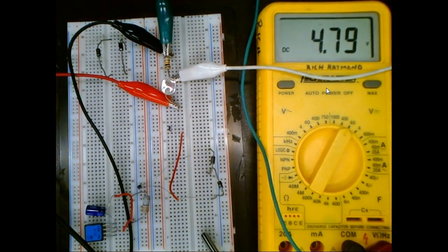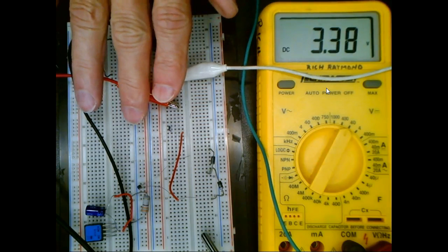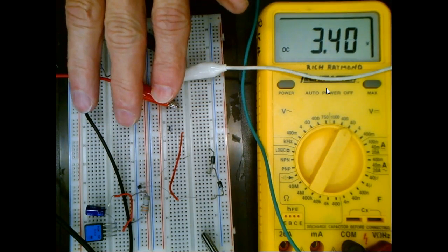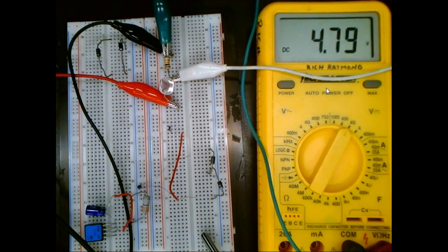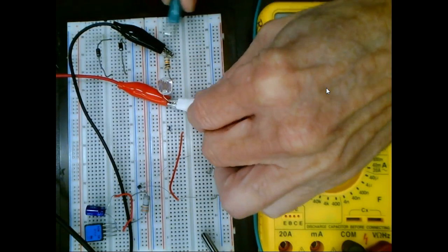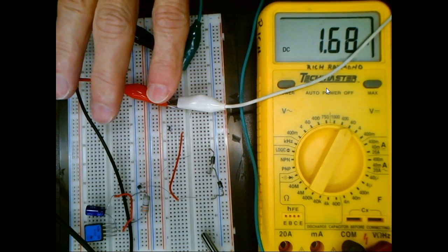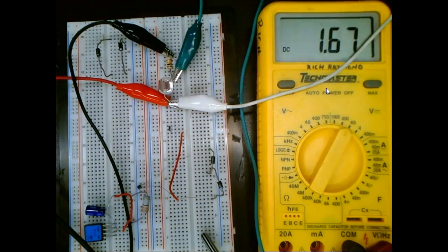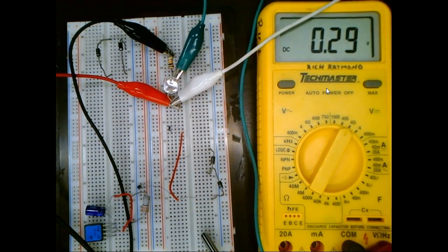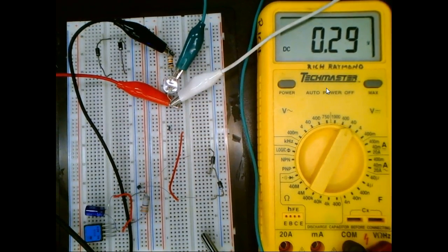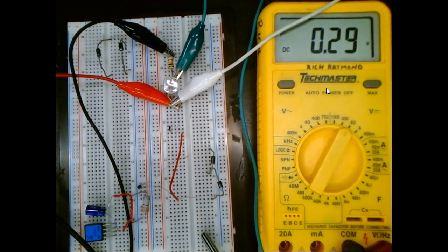So if the resistance of the photoresistor goes up, then the voltage drop across the what? The resistor is going to go down. I'm covering that real good, right? If I take my output across my photoresistor, then that means now it's going to go what? It's going to go up, right? So it all depends on what your system needs. And this is also true with the thermistor. So if you take it across the sensor, it'll go one direction. If you take it across the resistor, it'll go the other.